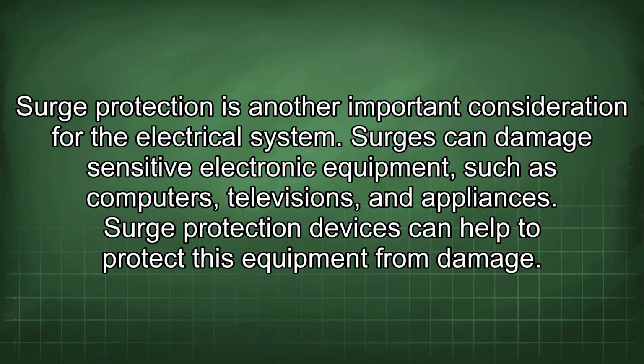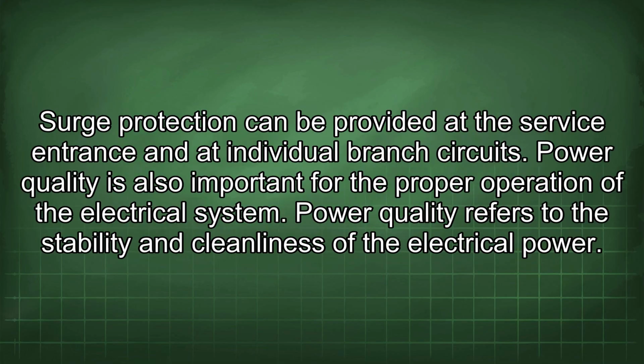Surge protection is another important consideration for the electrical system. Surges can damage sensitive electronic equipment, such as computers, televisions, and appliances. Surge protection devices can help to protect this equipment from damage. Surge protection can be provided at the service entrance and at individual branch circuits.